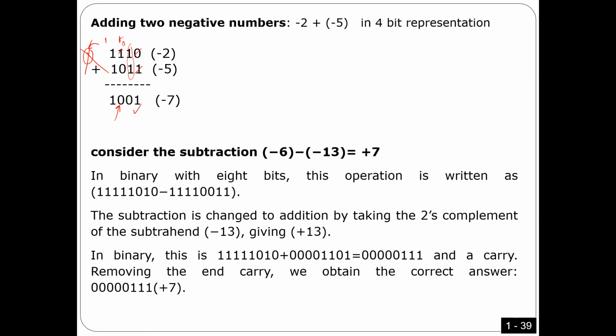So if you do it this way, I just did binary addition, similar to what I did before for unsigned numbers. So the same approach, you can use it for signed or unsigned. I got this result. If you do the conversion, you find this one is -2, this one is -5, and the result is -7. It's the correct answer. Signed or unsigned, it's the correct answer.